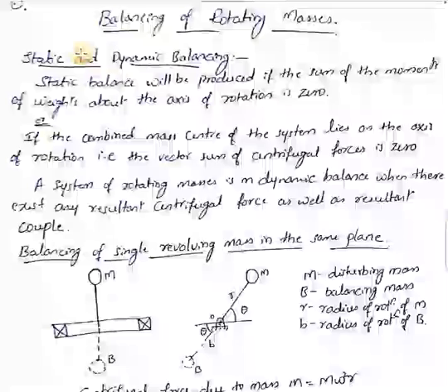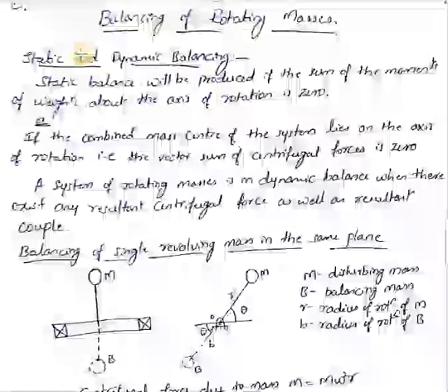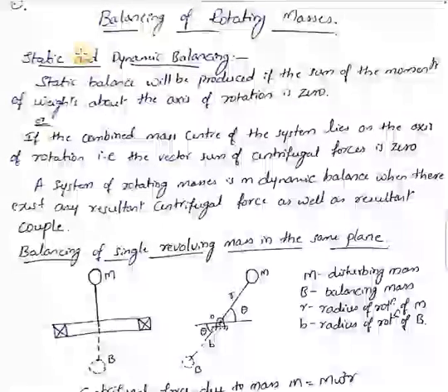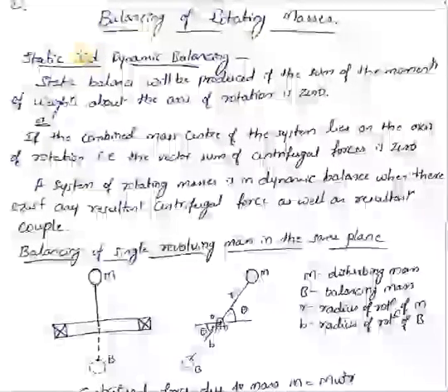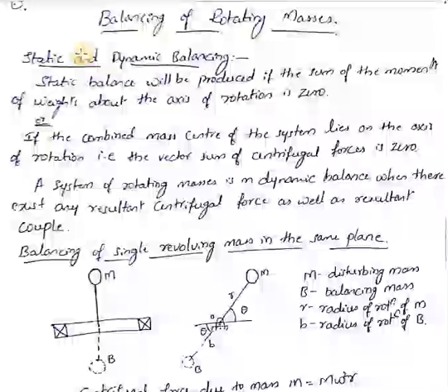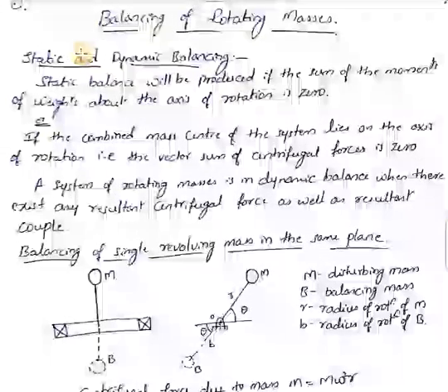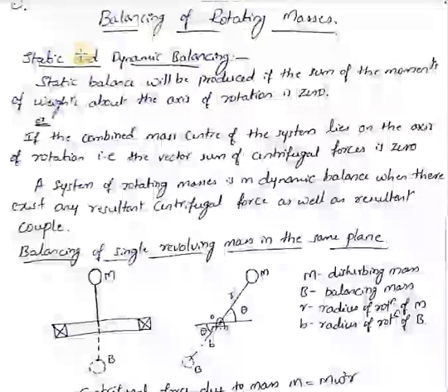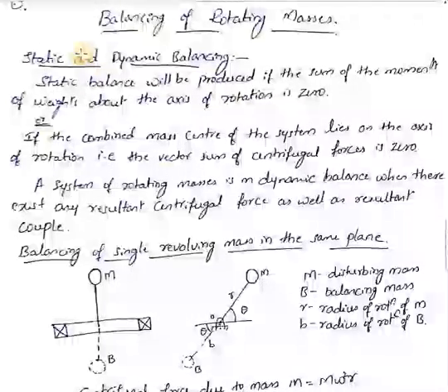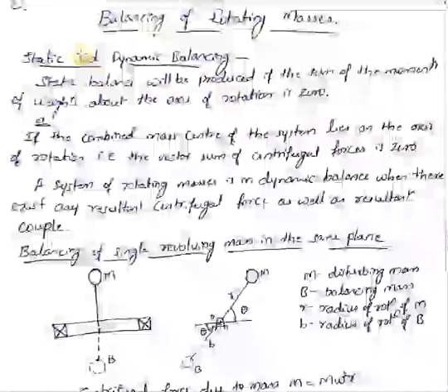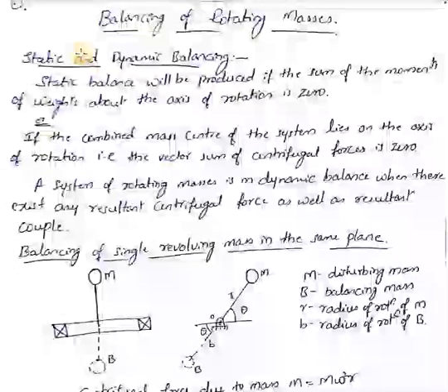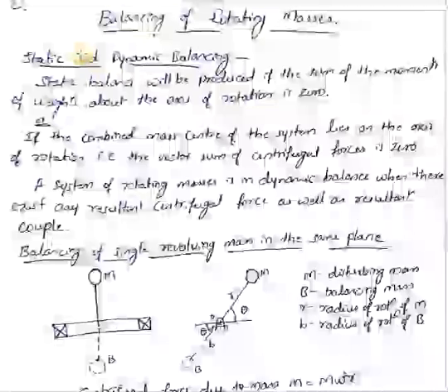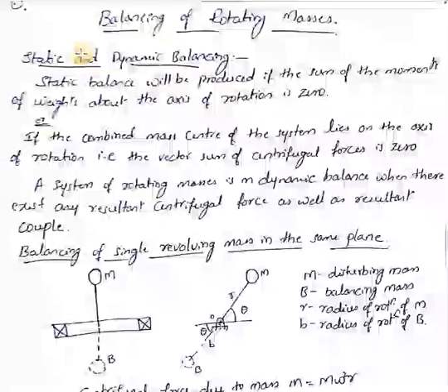Here, first we need to understand why balancing is necessary. High speed of engines and machines is a common phenomenon nowadays because machines are all designed for high speed. It is therefore very essential that all the rotating and reciprocating parts should be completely balanced as far as possible.